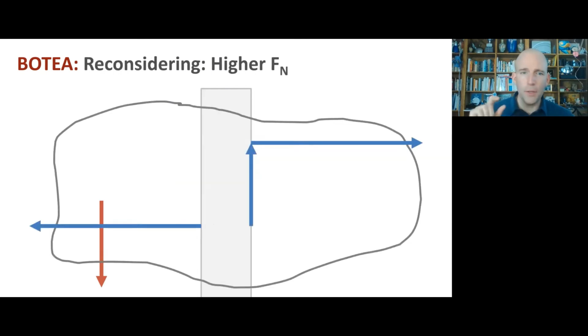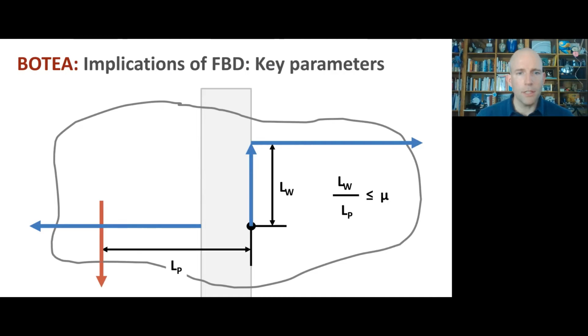Now, one thing to notice if we move from both wheels being driven to one wheel being driven is that we still need that vertical component of force to be equal to the payload. Now it's not distributed across two contacts, it's at just one contact. And so we need that friction force there to be twice as big, and therefore we need the normal force to be twice as big at each place. So there is a trade-off in that we need these bigger loads on our system, which could mean we need bigger structures. And as we think about what exactly those forces will be, it becomes helpful to think about the key parameters in our geometry from this side view.